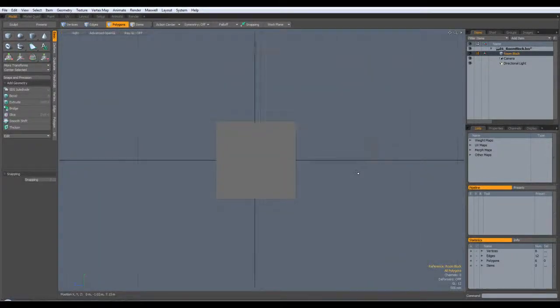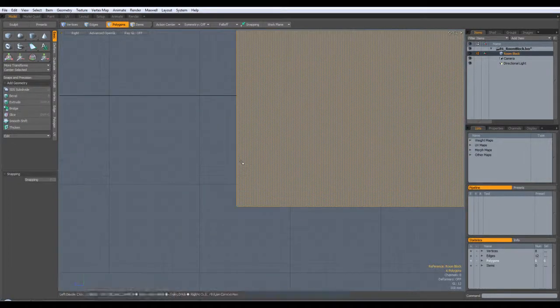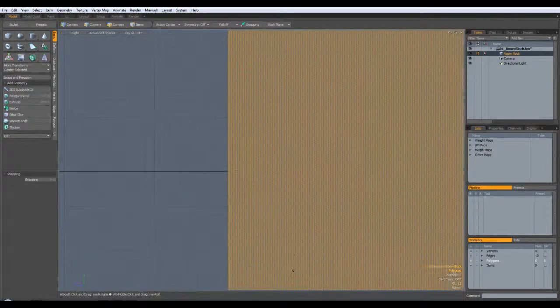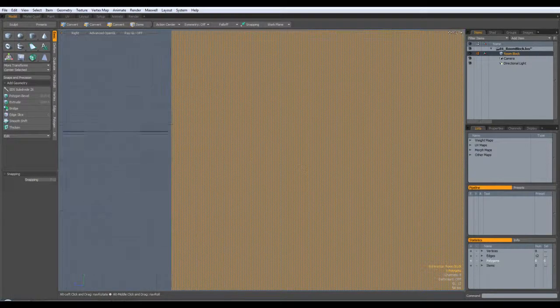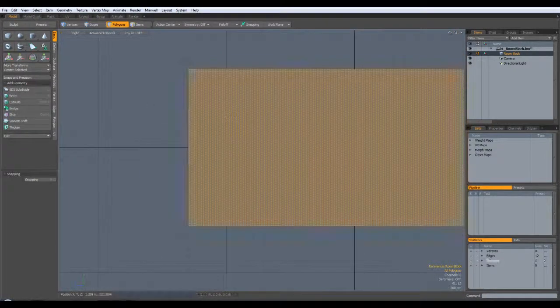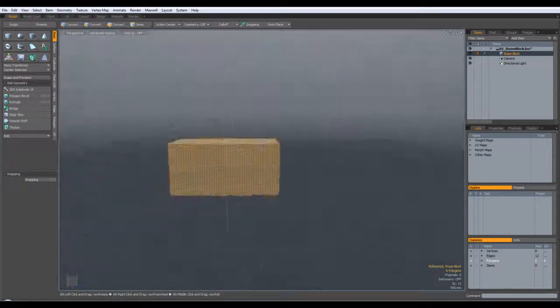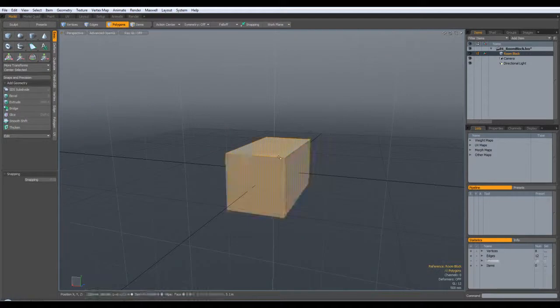Now on the number keypad here, you can jump through the views with the 1, 2 and 3. You just get a top view, a front view, and a side view. It's the right in this case, but to be honest, those 3 views are enough for you to do most of what you need in. Like I said, I'm just zooming in with the mouse wheel there, and to select objects, I'm just basically double clicking to select the whole set of polys,